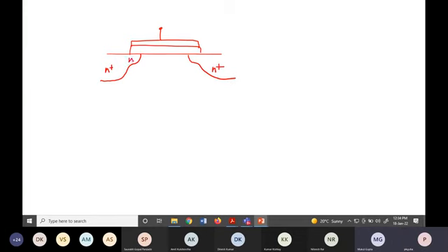In MOS, source and drain are basically symmetrical. So instead of forming this lightly doped region only near the drain, we also form it on the source side as well. What is the purpose of this lightly doped drain? Some part of the voltage will be dropped here. Whatever voltage you are applying between source and drain, some part of the voltage will fall across this lightly doped region, because this part is a little bit more resistive.